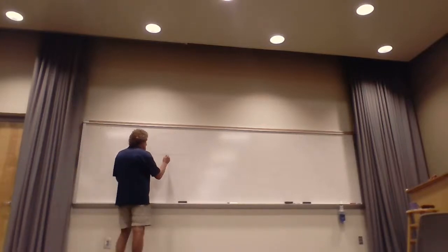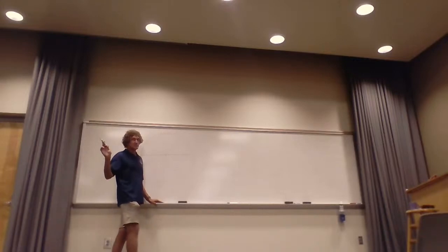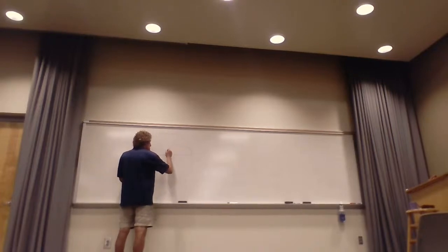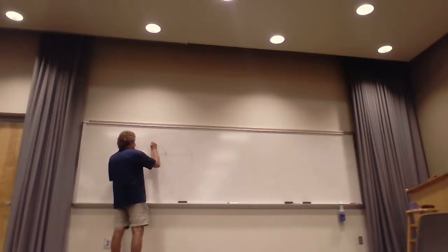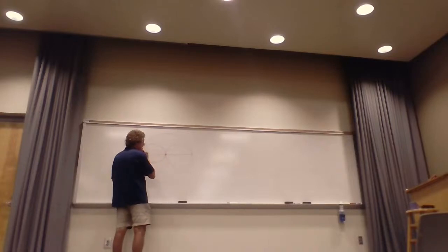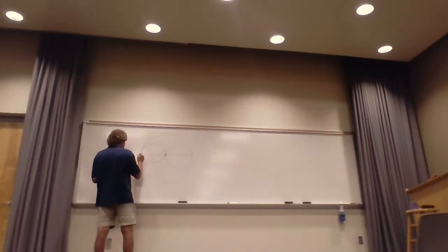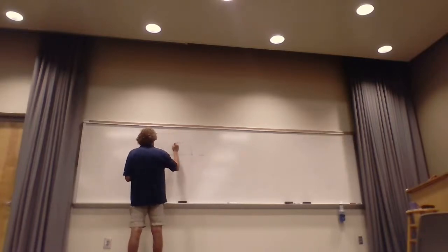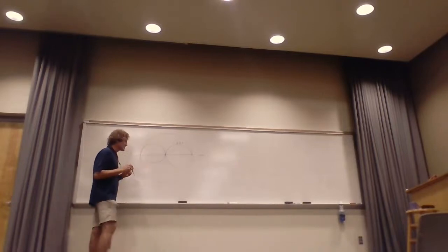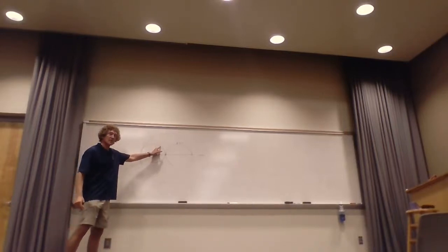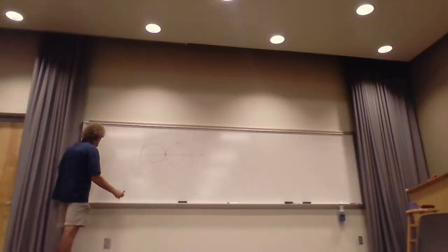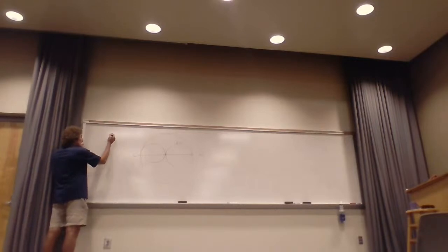So anyway, this is my Smith chart. Please, as many people as want, send me, Dr. Baginski, an email and I'll send you the rotated Smith chart. So here's the rotated Smith chart, like that. This is 0, this is infinity. This is the R=1 circle. That's the rotated circle. And it's important because any point on here corresponds with a conjugate point here when we do 1/. So when we do impedance matching in general, if we have a load